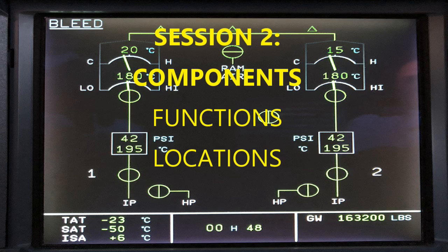It's not a good thing. So your OPV, short for overpressure bleed valve or overpressure valve, is also butterfly style, and it's going to be regulating and watching for that, because we don't want it to go past a certain amount.